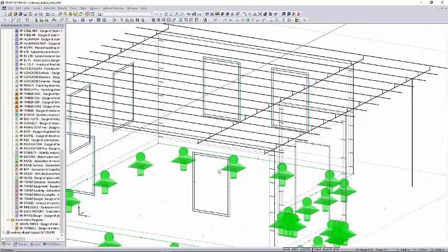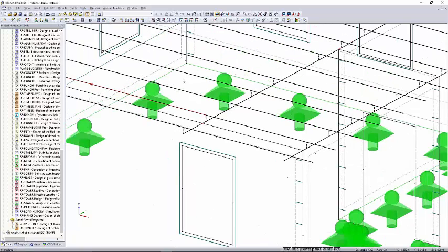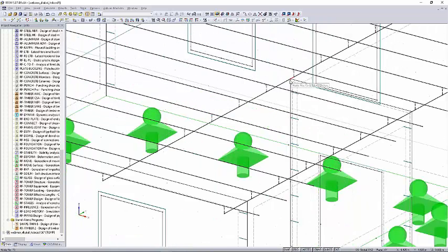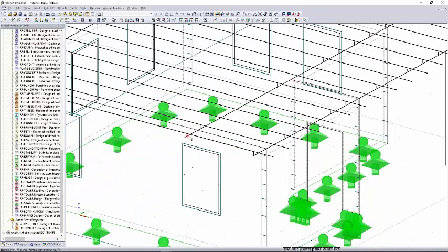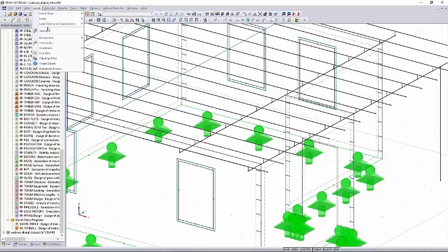What still is a little bit critical to see is that here the purlin goes completely over the wall, and there I would also like to smooth my results a little bit because there will be a critical singularity point, a peak, that can be avoided. In reality, you would probably define an average region here and here, like on every edge of it, but now I will just do it over the complete edge here, just to have it quicker.